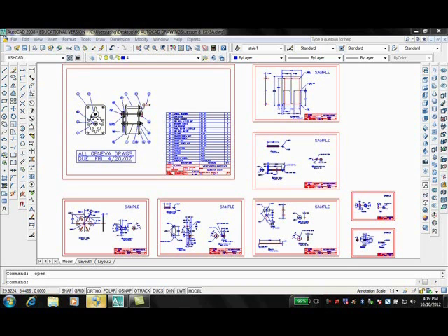If, however, we want all the drawings to be on B-size paper, 11 by 17, and the same format is inserted for a very small part, then it becomes necessary to scale down the format. The 2 drawings in the lower right corner will be plotted at a scale of 1/4. Therefore, the formats were inserted at 1/4 of their original size.